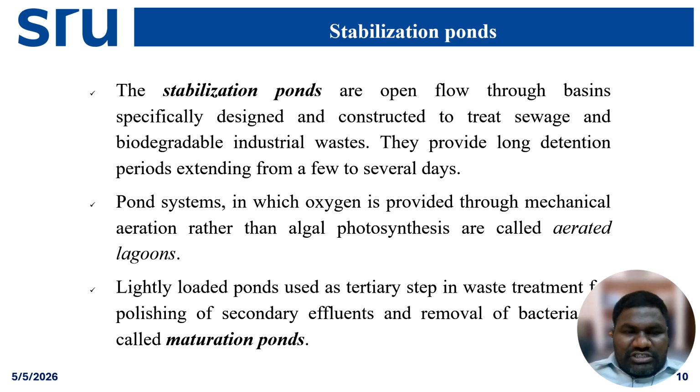A pond system in which oxygen is provided through mechanical aeration rather than algal photosynthesis is called an aerated lagoon. Lightly loaded ponds used as a tertiary step in a wastewater facility, for polishing of secondary effluent and removal of bacteria, are called maturation ponds.